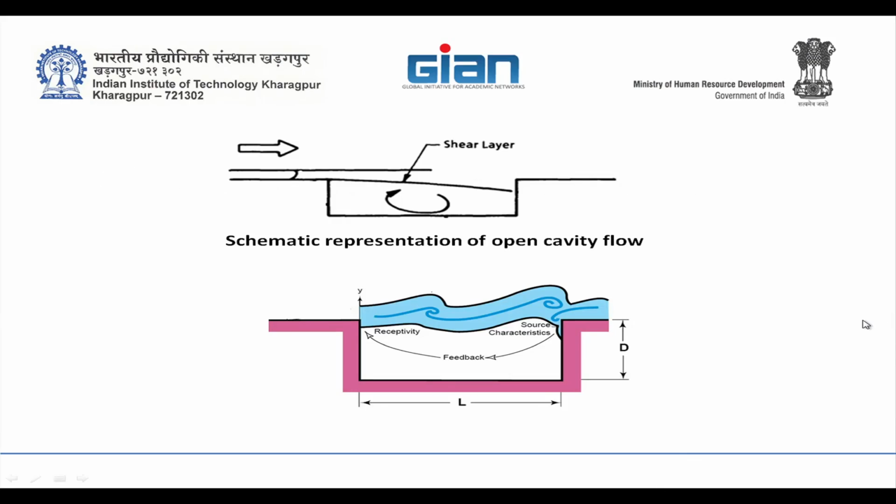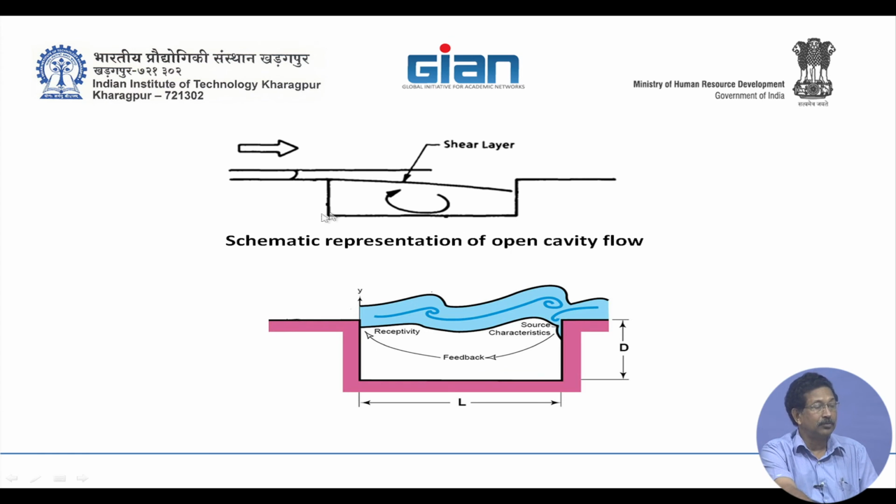So, in a supersonic cavity, see the schematic of the flow is like this. A boundary layer grows ahead of the leading face of the cavity, and here the vortices are set. The vortices are set at this leading edge lip, and these shed vortices are convected and impact at the downstream lip here. Once they impact at the downstream lip, an acoustic radiation starts because of pressure fluctuation,